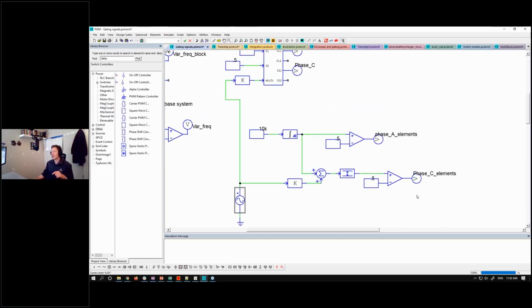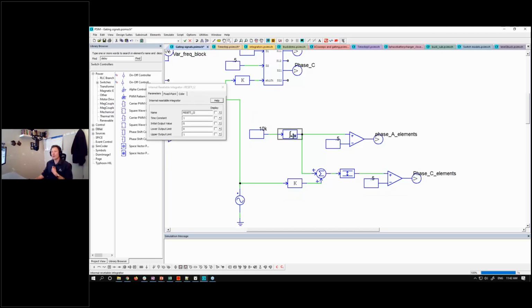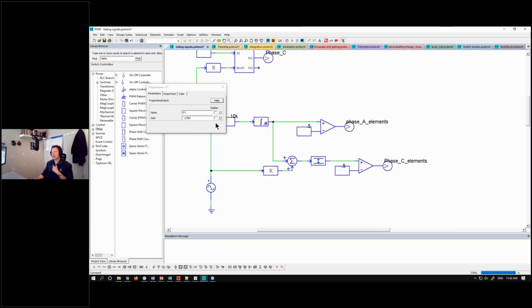And this is how that would get implemented under the hood. I'm using the same method as before, where I've got an integrator giving us a ramp that goes from 0 to 1 at the period we want, and I'm comparing with 0.5. My shift is accomplished by adding that shift in per unit, or in this case subtracting it because we want it to delay. Then we've got a range limiter, which ensures that we stay within 0 and 1 if we overflow. And then we just compare with 0.5 again.